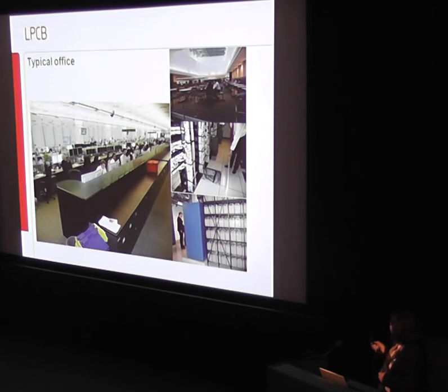And then there are other areas where they've got high ceilings, minimal fire loads. You've got your cabling areas in much tighter spaces. And this was a sort of battery backup area where all these plastic-contained batteries are within a space. Water mist arguably might not be the best solution for all these areas. You might look at gas, for instance, in the higher fire load space where you're actually wanting extinguishment.